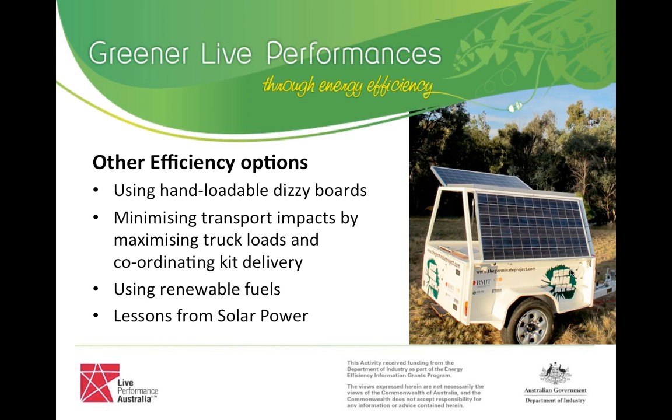Yeah. We can also see a loss of efficiency of our generators where the machines are subject to long light loads put on machines. Yeah, that actually damages the generators, doesn't it? It's not good for them at all. The rules of thumb we use are we try not to put less than 30% load on a generator, and we try to operate the machine in about the 80% of its rating range, and that seems to give us the best reliability and efficiency over the machines.